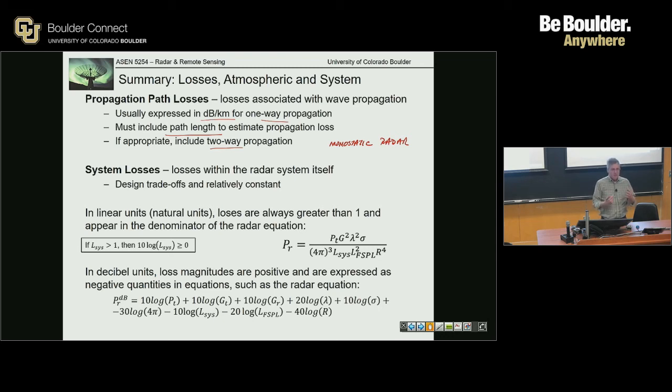And then noise. Noise is a random process. It's going to have some value with variation. If you take your samples, 240 range gates, and you don't have any targets out there, it's just measuring noise. So that's a good noise estimate. Oftentimes, if you're looking vertically for rain clouds, you transmit high enough so that there aren't any clouds above you, and now you measure noise. And now you get a noise floor.